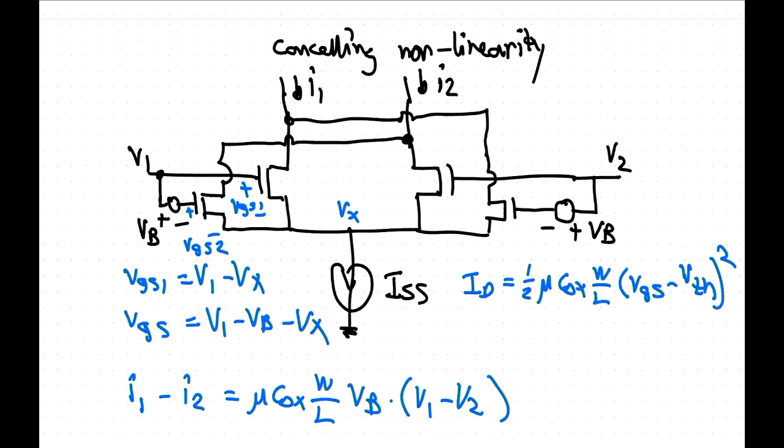There are a lot of different circuits which use a very similar approach, where you know the equations, and then you can cancel nonlinearities by having a number of different differential pairs that are biased with different currents or different voltages, and you add and subtract them. And you can keep going, to get second order and third order effects cancelled. Well, you can also do it with bipolar in sub-threshold, if you like, where you have an exponential function. It doesn't cancel out as neatly as that, but you can cancel it out to the order that pleases you by just adding differential pairs like that.